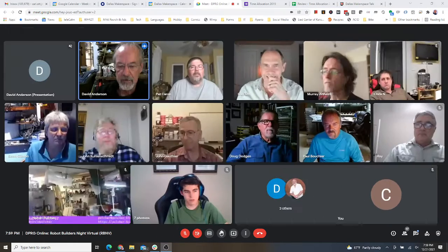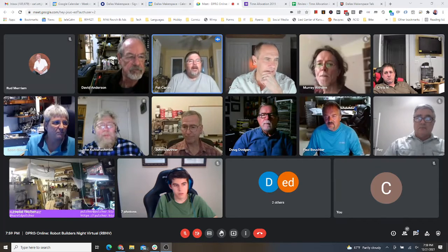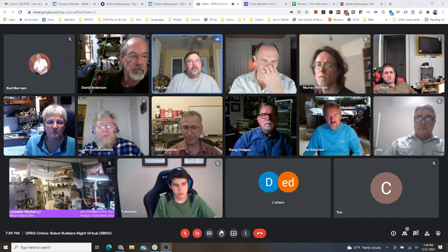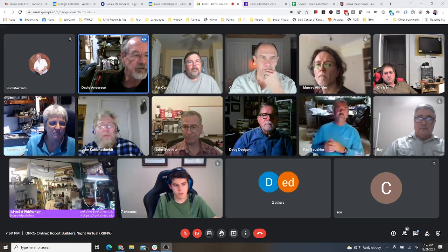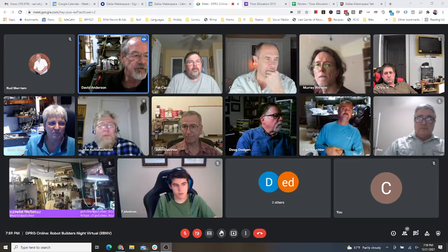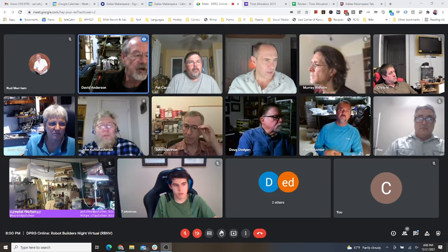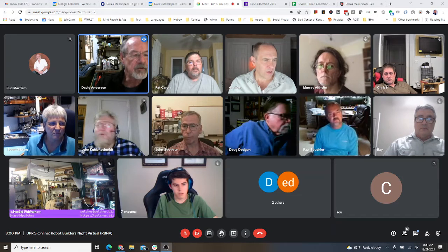Stop presenting. So David, you're running on one version or the other. You're either using your gyro all the time or you're using your wheel odometry to determine pose all the time. Exactly. So there's no Kalman filter or Wiener filter or anything like that that tries to determine which one is in more error. And as a practical matter, I would say that the gyroscope is almost always more accurate than the wheel odometry.